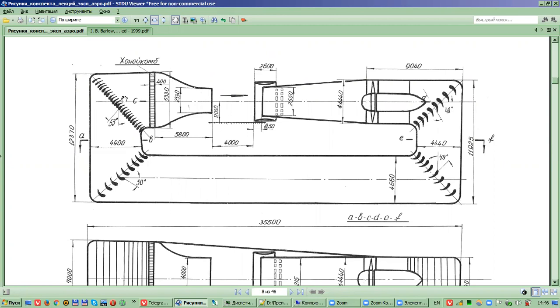This also depends on the desired turbulence level. When you need a small turbulence, when you need a laminar flow wind tunnel, you put a lot of screens after the honeycomb to break down vortices, smaller and smaller scale. Sometimes cells between wires are 5 millimeters, maybe 1 millimeter.